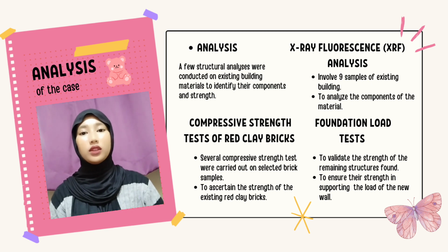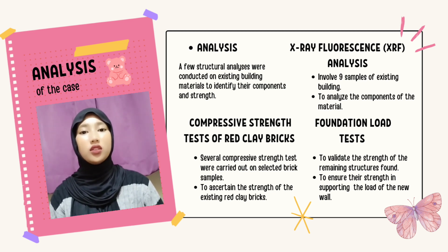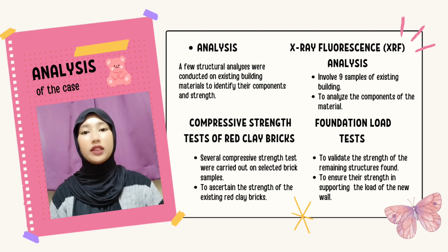An example of the load test result taken from one of the 6 identified locations is shown in figure 4. Failure shall be considered when the total residual settlement after removal of the test load exceeds 6.5 mm, or the total settlement under the design load exceeds 12.5 mm.